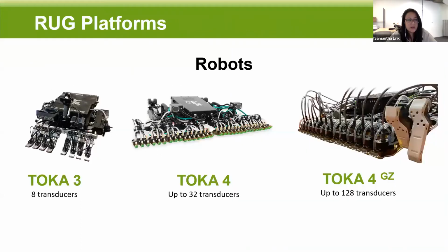Now, can robotic platforms for RUG inspect elbows? So right now we're limited on what we can do with elbows. We can cross the elbow on the flat side in most cases, in most diameters, and most curves, to transition to the other side. And we can take some readings as we're doing that. But we can't get the outer radius and the inner radius right now. We're working on that solution with our newest platforms. But right now we cannot.